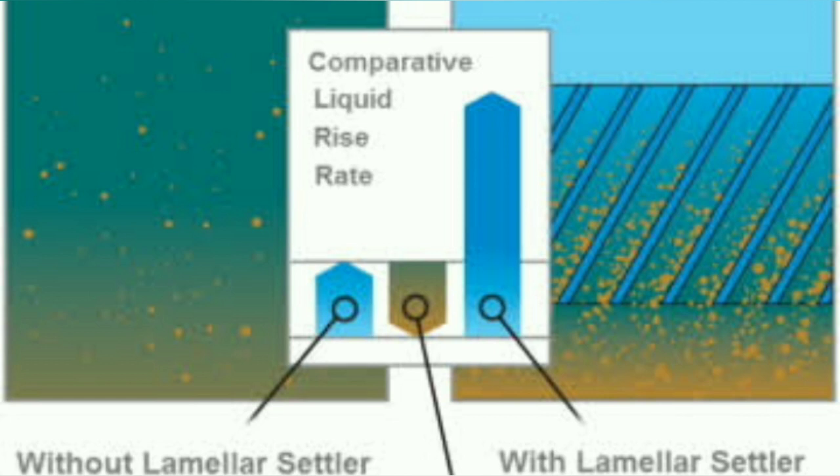The tube settler channels collect solids into a compact mass which promotes the solids to slide down the tube channel. But when we compare to the plate settlers, cleaning of this is quite difficult. But apart from this, it has many advantages when we compare with the others. Clarifiers, when equipped with tube settlers, can operate at 2 to 4 times the normal rate of settling of clarifiers. So it is possible to cut the coagulant dosage by up to around half for maintaining the lower influent turbidity. So it has two advantages.